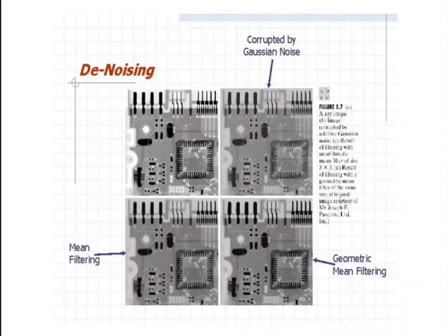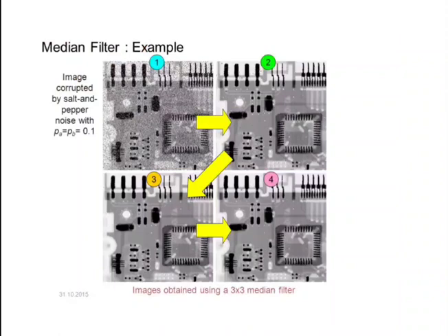The positive order filter did a better job of clearing the background at the expense of slightly thinning and blurring the dark areas. The opposite was true of the negative order filter. In general, the arithmetic and geometric mean filters are well suited for random noise like Gaussian or uniform noise. The contra-harmonic filter is well suited for impulse noise, but it has the disadvantage that it must be known whether the noise is dark or light in order to select the proper sign for Q.